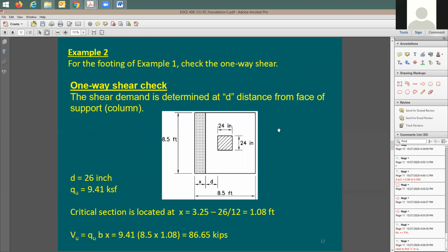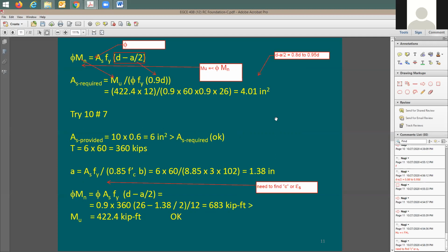All right. Excuse me. Yes. Why don't we, from the beginning, assume that the steel is in the tension control section, I mean, epsilon t equals 0.005? Very good question. Instead of actually putting d minus a over 2 or 0.9 d, if we initially assume that steel strain is 0.005, then we can easily calculate the c with that similar triangle.